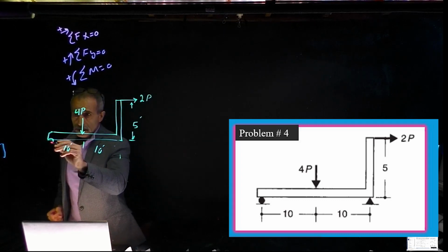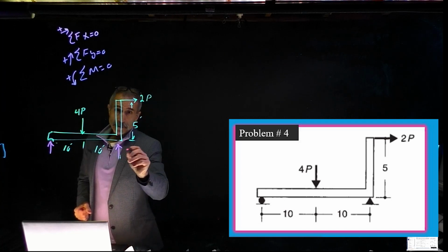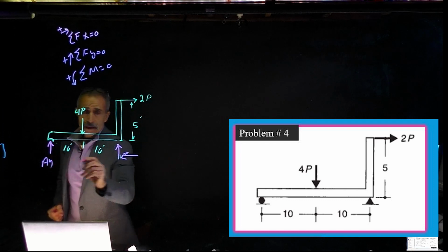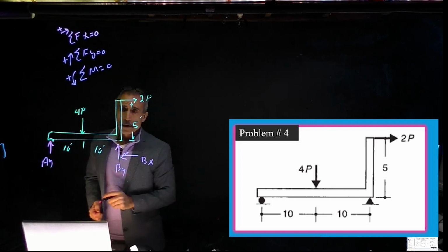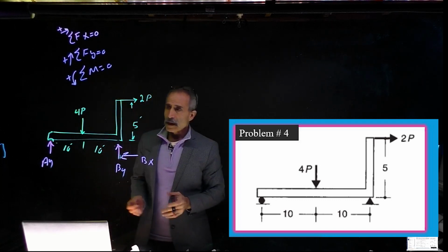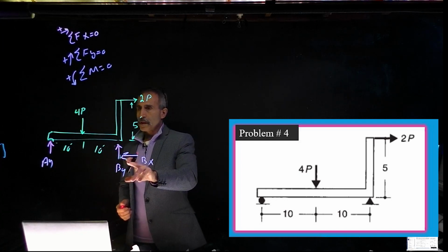Instead of the reaction, I'm going to replace it with the force. So it's going to be AX here, and here we're going to have AY, and this will be BX and BY here. So we'd like to know what the reaction forces are here. We can take a moment about here or here. Let's go ahead and take a moment about point B.